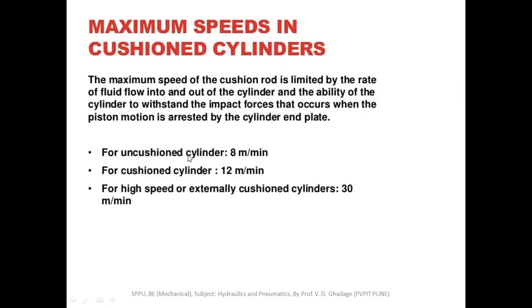For an uncushioned cylinder, 8 meters per minute. For a cushioned cylinder, 12 meters per minute. For a high speed or extremely cushioned cylinder, 30 meters per minute.